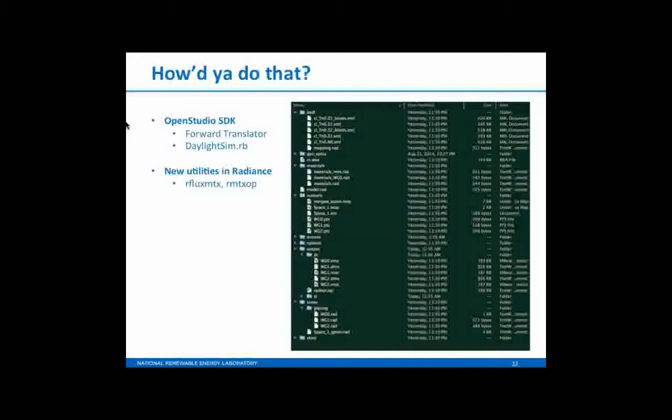So we're making some assumptions for you. The goal is down the road that the user will just be able to pick any BSDF they want or make their own BSDFs and assign them to specific windows, or even have more than one BSDF. So in theory, you could do electrochromic glazing that maybe has multiple tint states and stuff like that. It opens up a whole lot of possibilities.